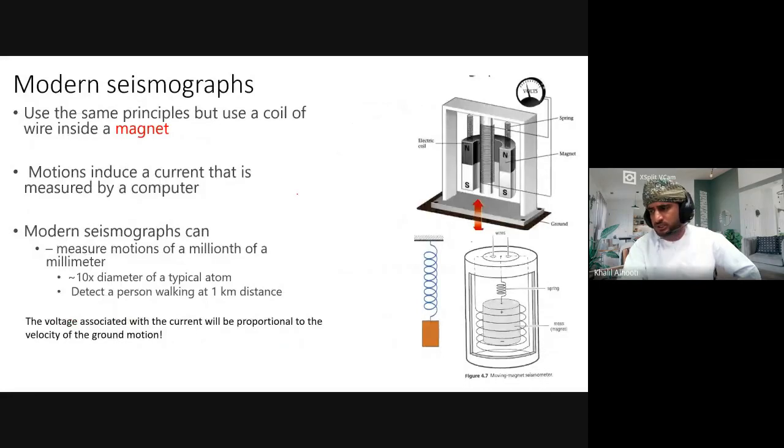Nowadays we are using such type of instruments, especially geophones. So this is a geophone. The only difference is that there is a spike, and we dig the spike into the ground when we do the recording. This is the inertia mass, the thing which keeps moving. The magnet is the inertia. The magnet keeps moving whenever there is shaking, whenever there is a movement, and the movement is converted to a voltage. That's what we record, and we save it.